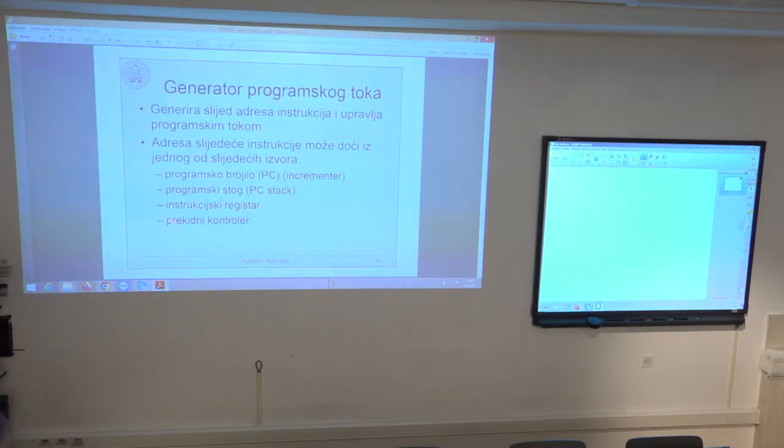The same thing is with interrupt request servicing. So if the interrupt occurs, then this current program counter is written on some hardware stack, I will describe later on. And after servicing this interrupt service request routine, the final instruction, return from interrupt, will again pop the value from this program stack and write this value over the program counter just to go back to the main program where this execution was interrupted by interrupt request.